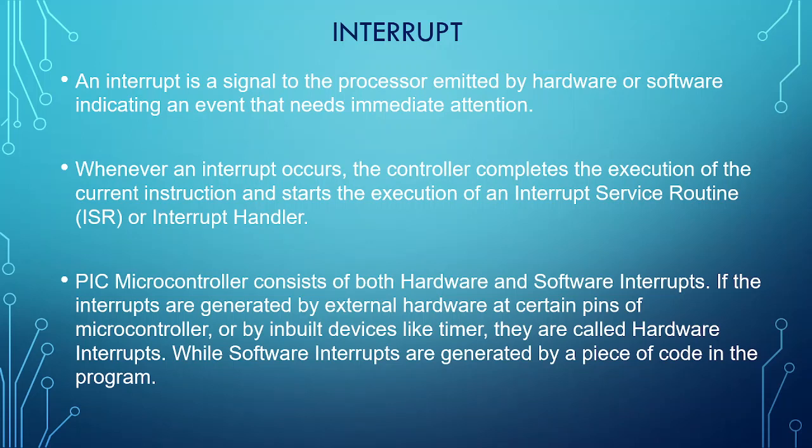PIC microcontroller consists of both hardware and software interrupts. If the interrupts are generated by external hardware at a certain pin of the microcontroller or by inbuilt devices like timer, they are called hardware interrupts, while software interrupts are generated by a piece of code in the program.